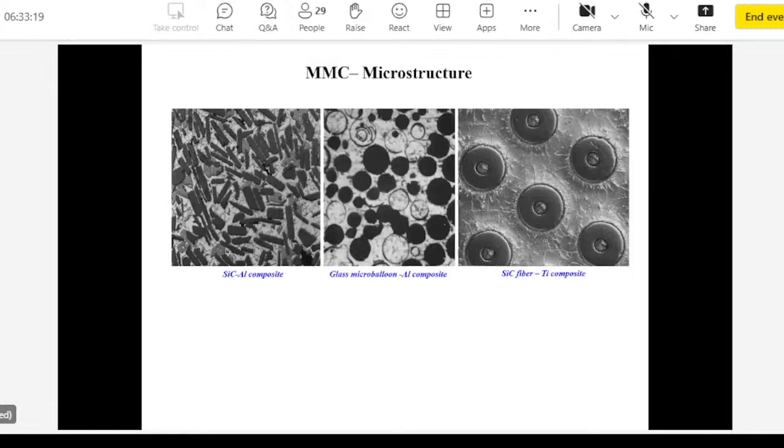These are some pictures of composites made using powder metallurgy on the top, and the same composite made using metal casting process. In metal casting, temperatures are much higher, so there is a lot of reaction. The fiber matrix reaction is less in powder metallurgy composite.